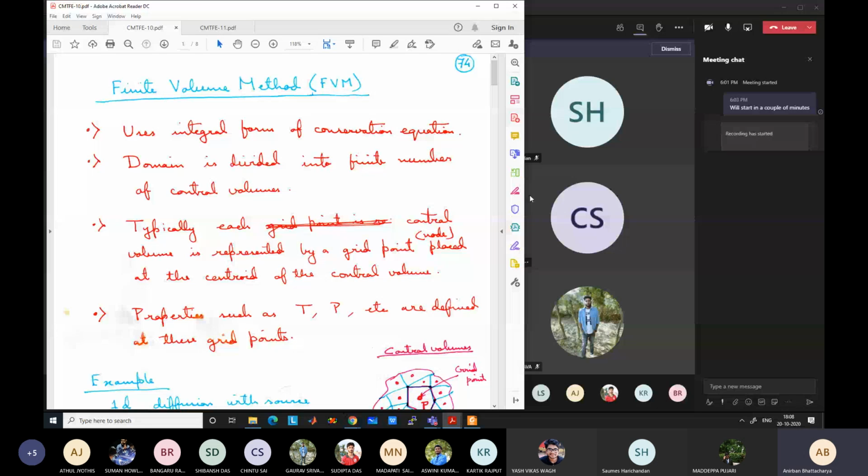Okay, I'm back. Which means that we can tackle complex physics using the finite difference method if the geometry is simple. There can be two types of complication in a CFD problem. The geometry can be very complex, or the geometry can be simple. Complex geometry means, say, you are designing a complex casting or some flow channel with very intricate details, but the physics may be very simple. Say normal flow is occurring, with not much chemical reaction or anything else. On the other hand, we can have a very simple geometry but very complex physics.